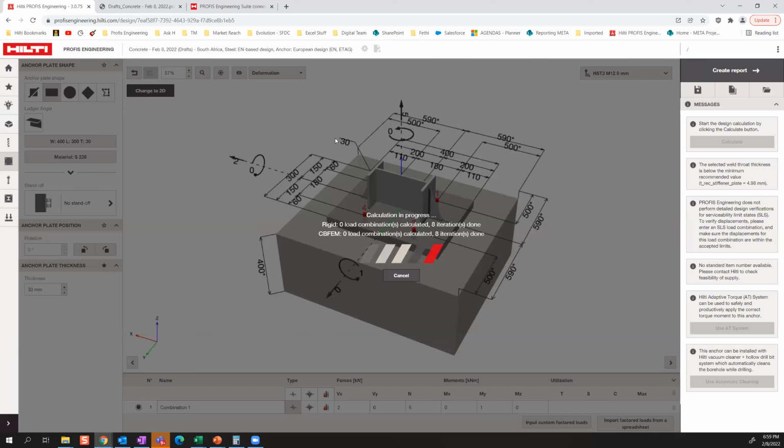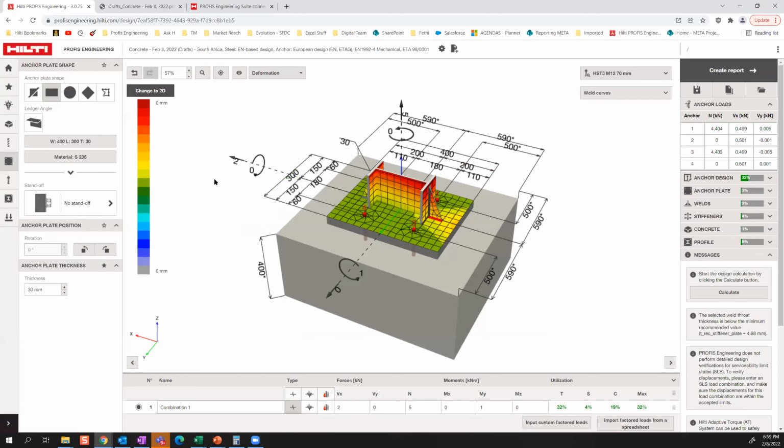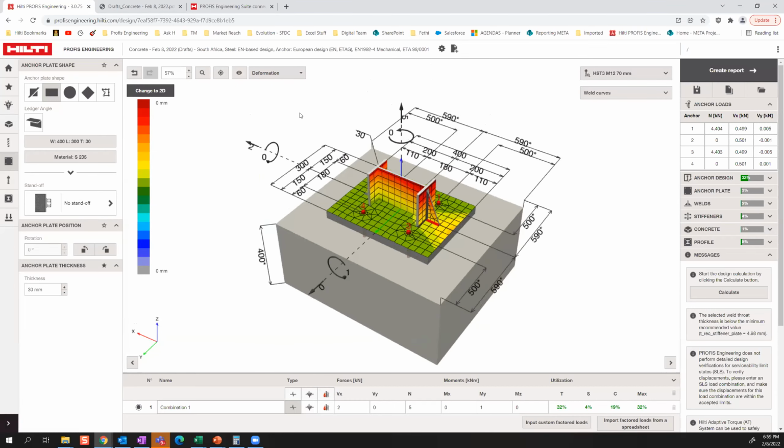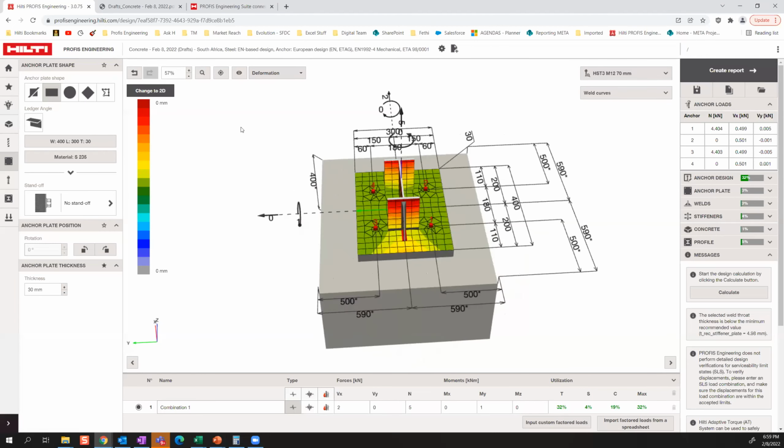He's gone and increased it now, and you'll see that it gives you a very different solution. First I did 8, now second I did 15, now I'm trying 30 and then see what happens. As you can see, it was 49%. Now, because it's 30 mil, it's basically down on the anchor forces because of the prying forces being reduced. And the difference is about 16%. But again, is it optimal? Probably not. So it's just a case by case study of these.